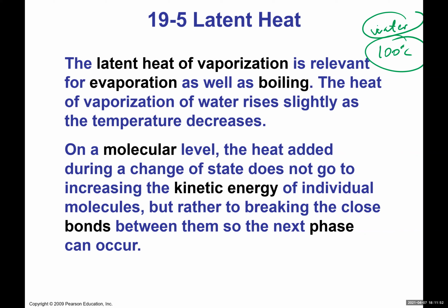The heat of vaporization of water rises slightly as the temperature decreases. On a molecular level, the heat added during change of phase, change of state, same thing, does not go to increasing the kinetic energy of individual molecules. That's why the temperature doesn't change, but rather to breaking the close bonds between them so that the next phase can occur. Okay, so you can think of it like this. For the ice cube, a solid ice cube, those are the molecules, and they are all bound to one another with, let's say, spring-like forces.